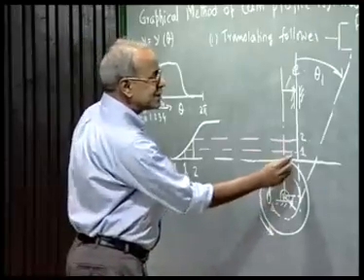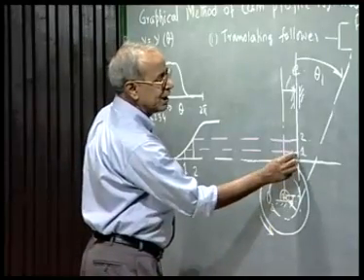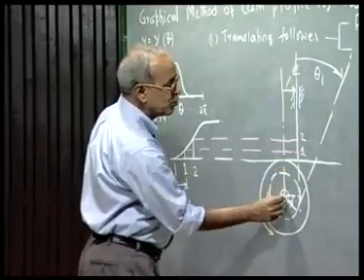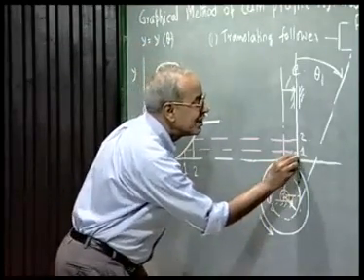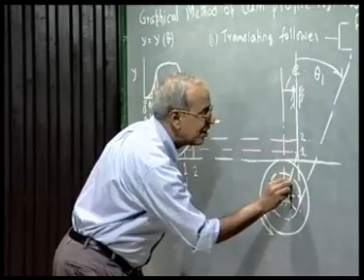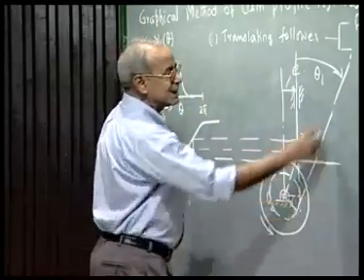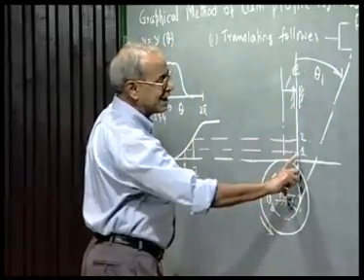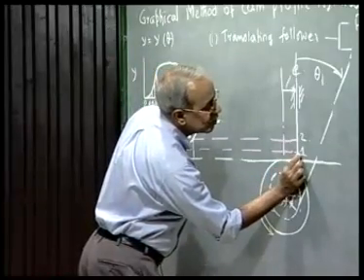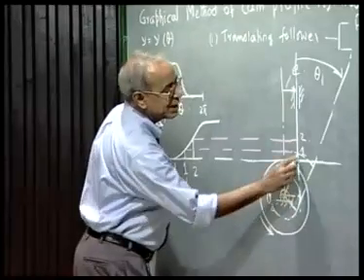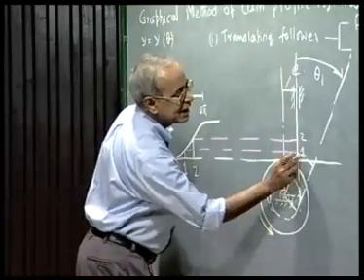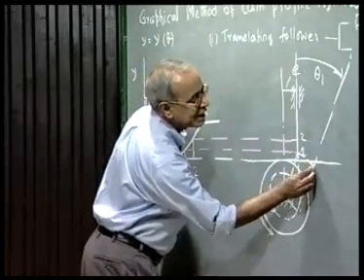Now, the distance of this point corresponding to station point 1 from O2 is here. So, this is the distance. This line represents the follower axis, and the point should be at this distance. So, I rotate this radius along this circular arc and intersect here.